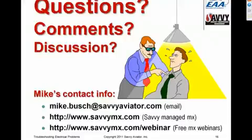By regulation, and of course the Citabria is a certificated aircraft, anything that is hot wired to the battery, in other words, that continues to be powered up when the master switch is turned off, is required by regulation to be protected by a fuse. And that fuse normally has to be within a couple of inches of the battery itself. So normally, if the aircraft has hot wired items, as I said, like a clock or a courtesy light or something that is energized even with the master switch off,